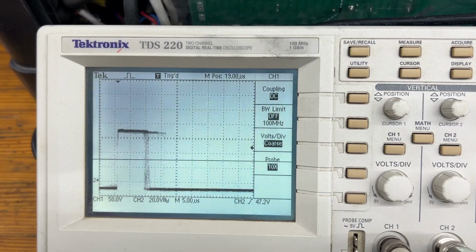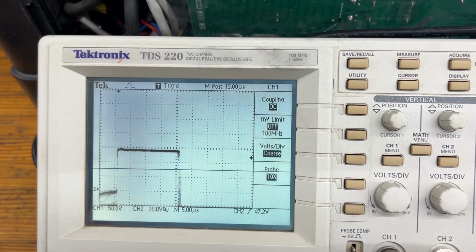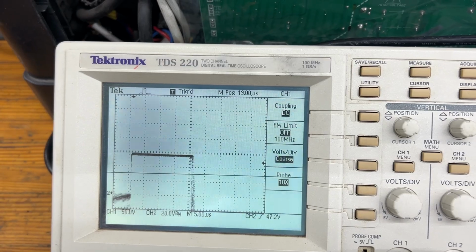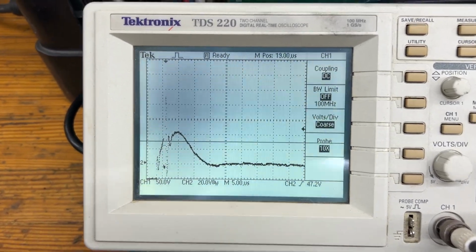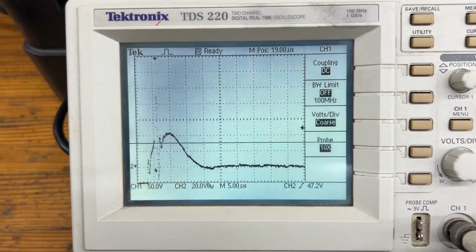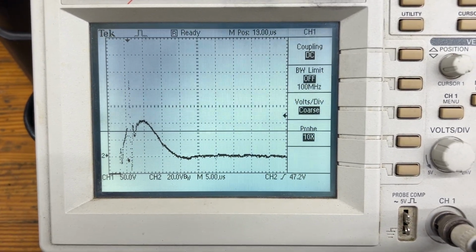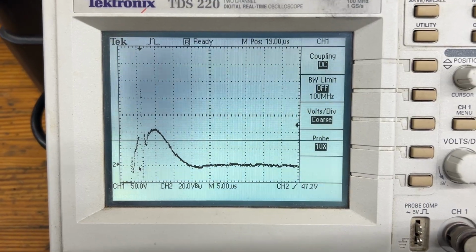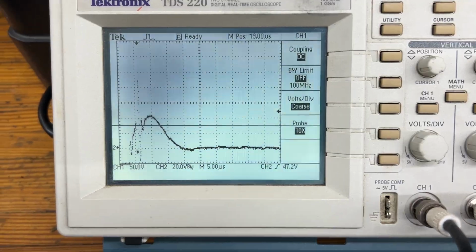There is the waveform. I was just assuming this was a straight up variable DC control for RPM, but it's a little more sophisticated in the manner of the control. It is pulse width modulation. But I think I see the problem.